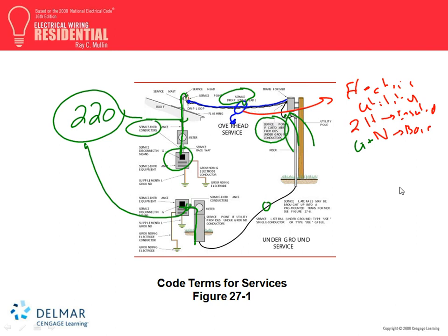Yes. That's my point. What you're saying is, if I'm an electrician, I'm not going to tie it into their line. When you talk about this 7200 volt, not there, but on the other side of the transformer, guys, if the cables are outside, you can tie to the secondary. That's 220, that's 120/240. You can tie to these cables temporary, where they allow us to go tie them temporarily, and then they come and permanently connect them.